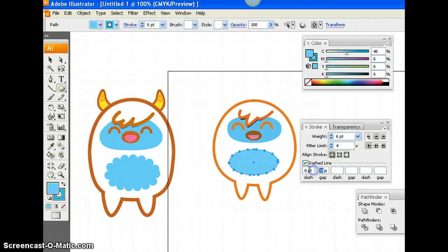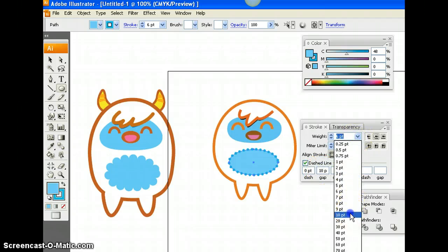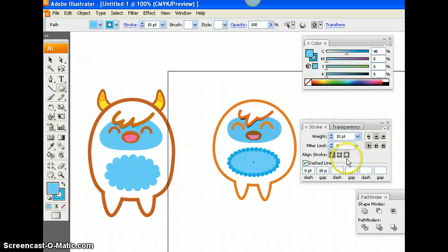And let's play with this now. Let's make that 30, nope, let's make it 10, oh, getting better. Let's make the weight stronger, that's getting better. And let's change the color a little bit. How do we change the color of the dash? Oh, that's right, stroke. Just to try and get those colors the same. There must be a better way, and I'm sure we'll learn that as we go through this Illustrator course. And there's a trick for creating that.